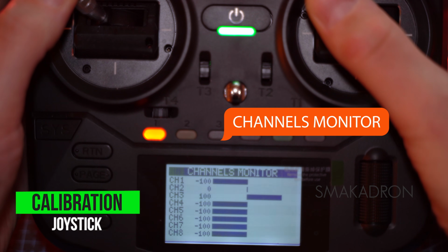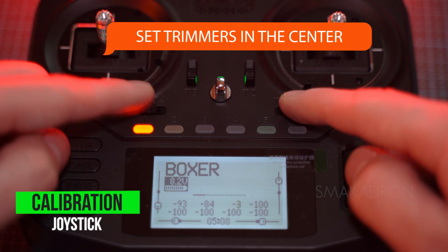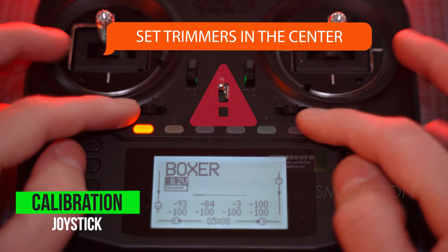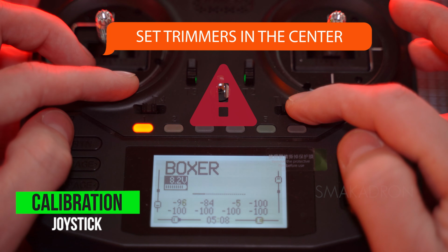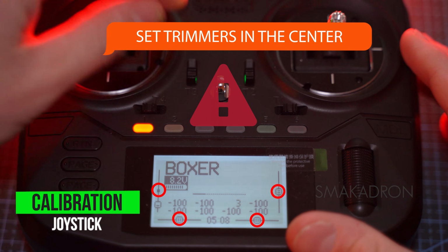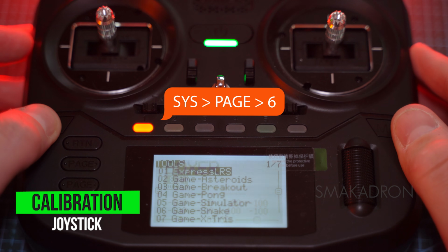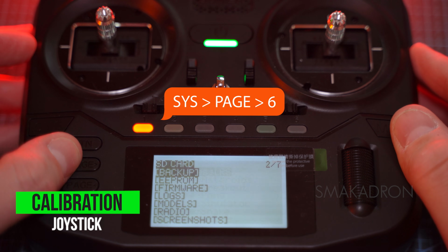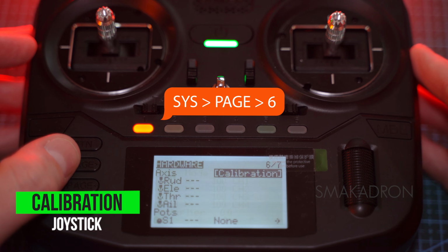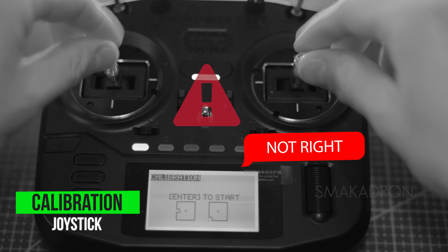To calibrate your radio, you need to do the following. Go back to the main menu of the radio. First, it's important to set the trim values to the center position for all 4 axes. Then, press the System key. Using the Page key, go to page 6, titled Hardware. Then, press Calibration, and enter again.